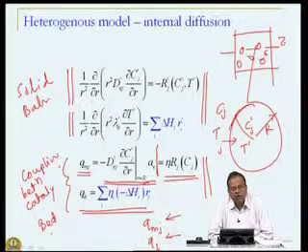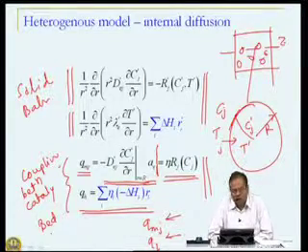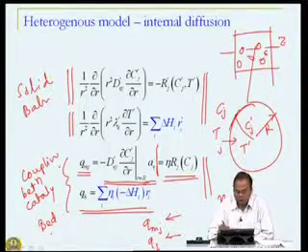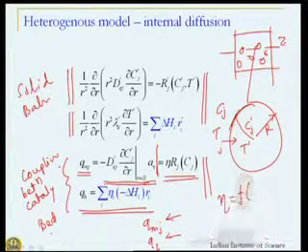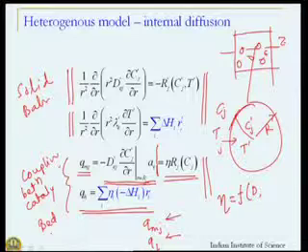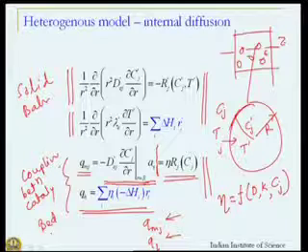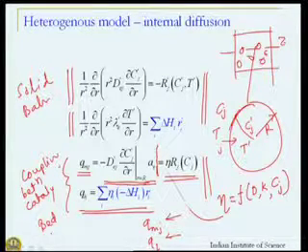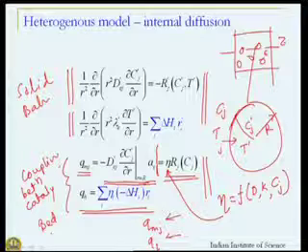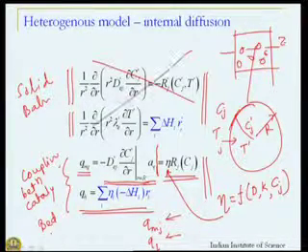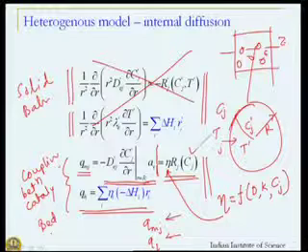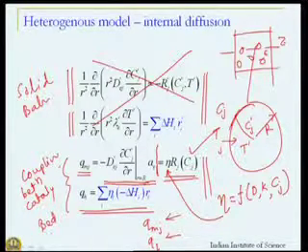But what if I had, a priori or independently, calculated my effectiveness factor as a function of, let us say, diffusive characteristics, reaction rate constants, and bulk conditions? If I had this knowledge a priori, I could have substituted it over here, and without solving these mass and energy balances, I would have simply got the coupling that I require to solve my reactor balance. And this is why this effectiveness factor approach is popular